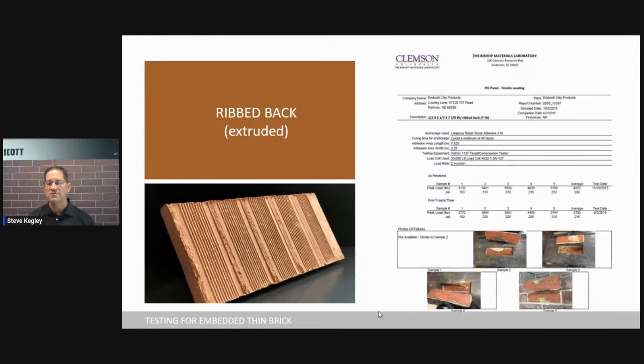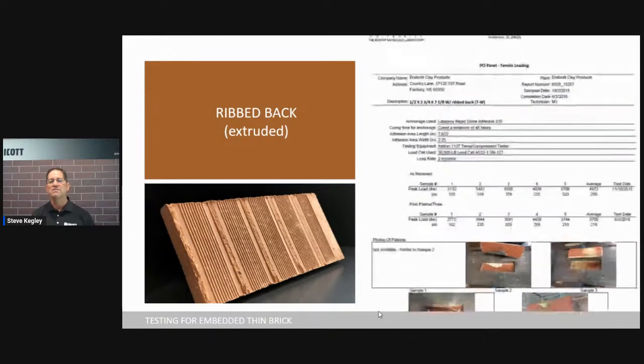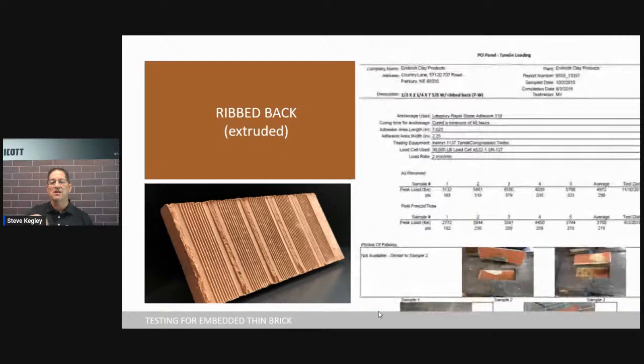You can see the photographs down here, and then they run it. They do all the measuring on the first line there, the top line, when it comes right out of the pack, and they do all of that testing. Then they run it through 300 cycles of freeze thaw. Okay, so 300 cycles, that's the testing requirement.